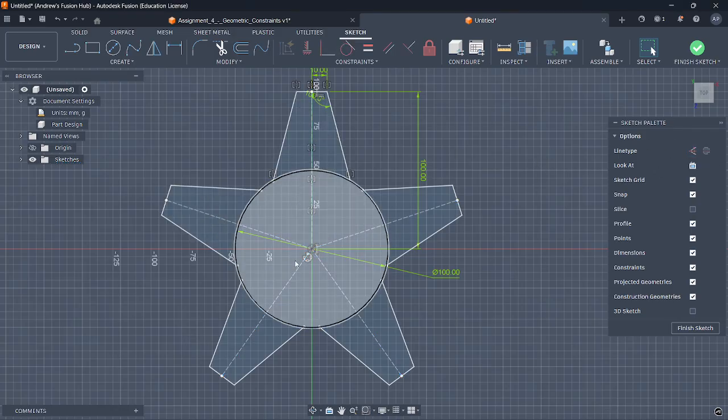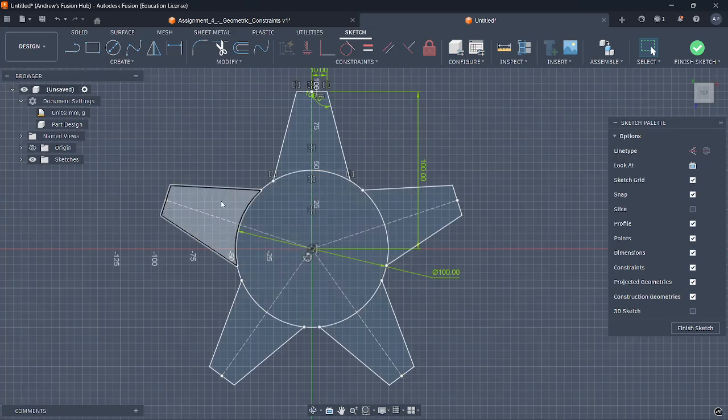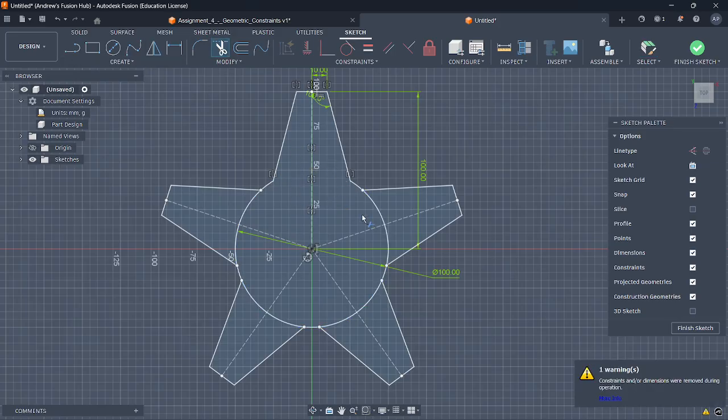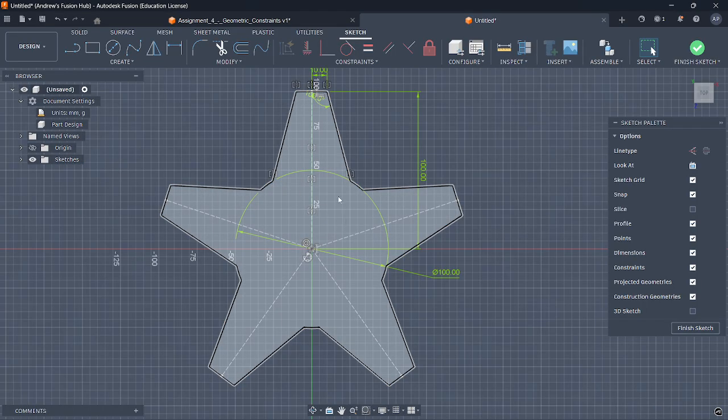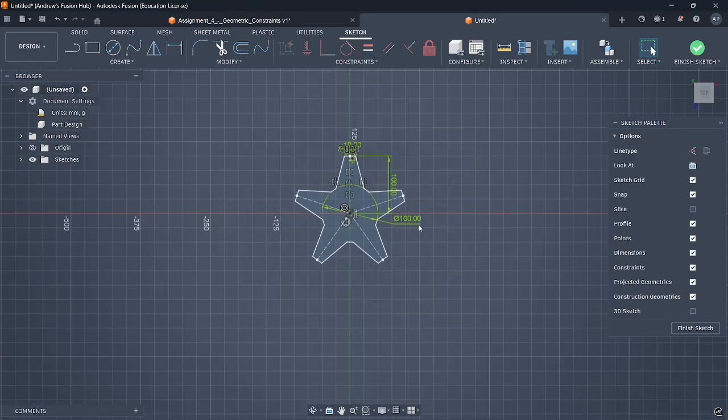you can see it greatly reduces the number of closed areas that I can highlight, right? You can see this whole circle's being highlighted now. It's not like a little slice of a pie, it's the whole thing. And each tooth is its own closed body. You can even go further by trimming away the excess of these little arcs on the circles. So I could go like this and trim it away. And now it's one whole closed body, right? You don't have to do that, but that is an option.